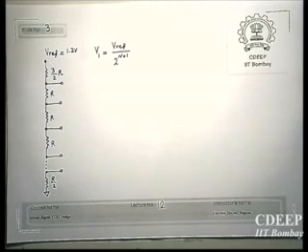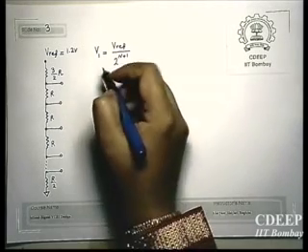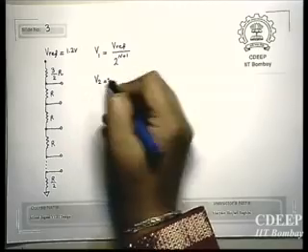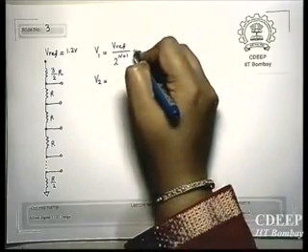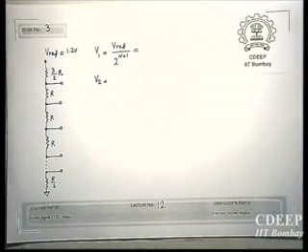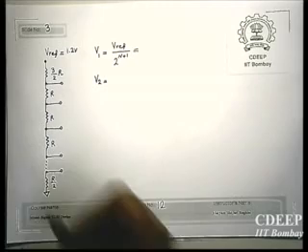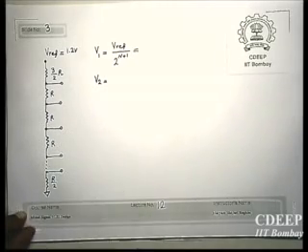Okay, and then we will continue. Therefore, in general, say for example, now V2. Now, how is this generated? Eventually, suppose for example, you have n number of bits. Therefore, what you need will be 2 to the power n comparators. Each one of these reference values goes to one comparator.